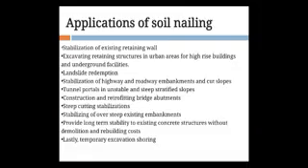Now, application of soil nailing. Stabilization of existing retaining walls is one application. Excavating a retaining structure in urban areas for high-rise buildings and underground work: the excavation is much deeper, so soil nailing is introduced there to restrict the soil from falling down.